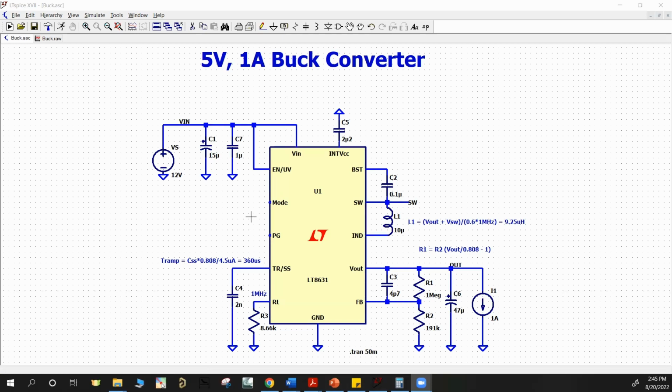It's also good to play around with some of the passive values and see, for example, how changing the step on the output load will change the performance of your switcher IC. So I really recommend you simulate your switcher ICs before designing an actual PCB.